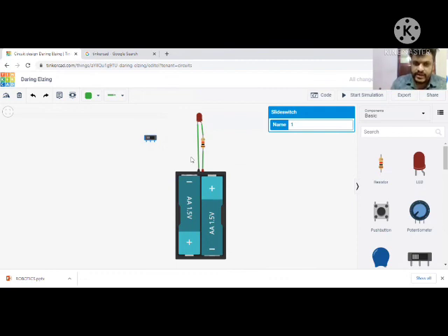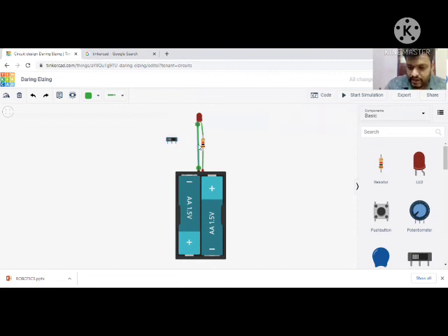In the same manner, in this circuit, we place this switch here. Now I will remove this, and I will show you how to connect this. We do not need to change this connection. Now let me take this from negative. I give connection to the common of this switch. From terminal 2, I connect it to the cathode. Now our circuit is completed.